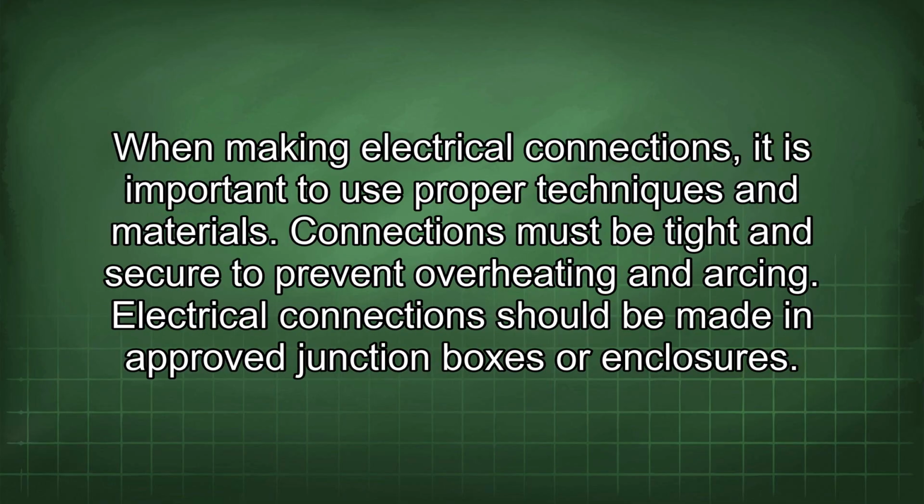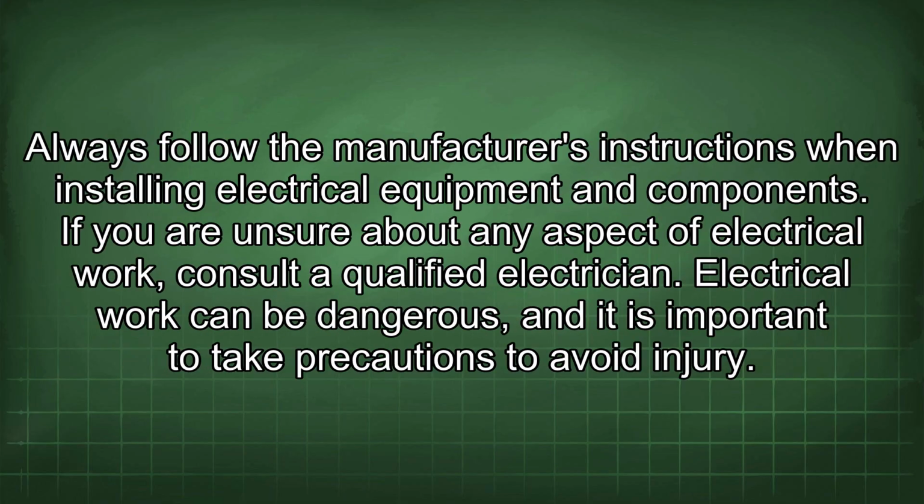When making electrical connections, it is important to use proper techniques and materials. Connections must be tight and secure to prevent overheating and arcing. Electrical connections should be made in approved junction boxes or enclosures. Always follow the manufacturer's instructions when installing electrical equipment and components. If you are unsure about any aspect of electrical work, consult a qualified electrician.